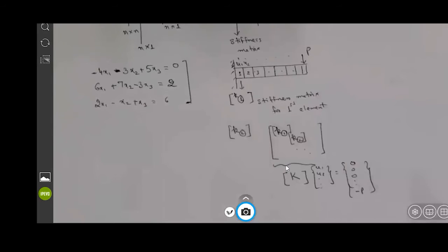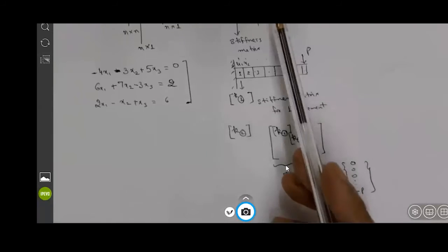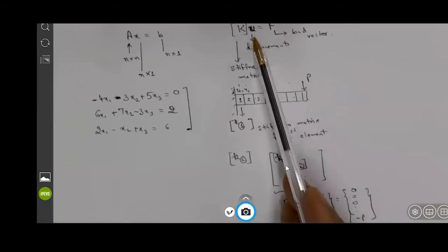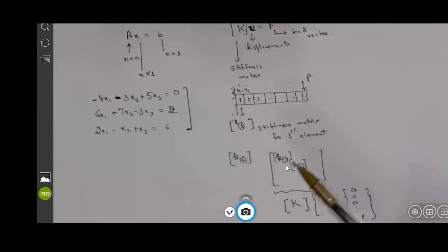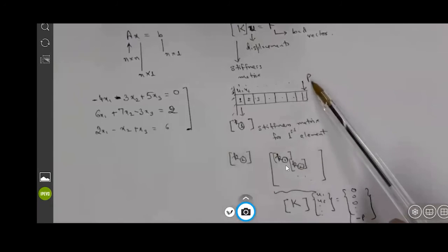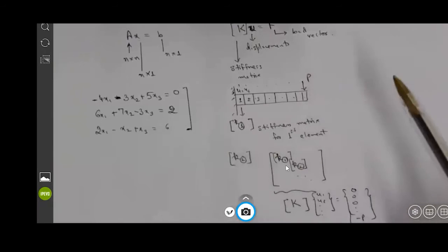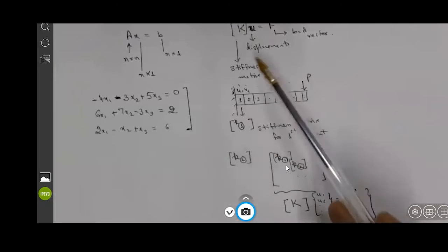It's an example of a mechanical load or mechanical finite element methods where you're actually solving a big system of equations and you're interested to find the displacement. Now, when you are doing these calculations, you are not doing this only once. If you have to do multiple iterations, suppose it is a nonlinear system, or suppose P is a time varying load, then for every time increment, you have to solve this system of equations.